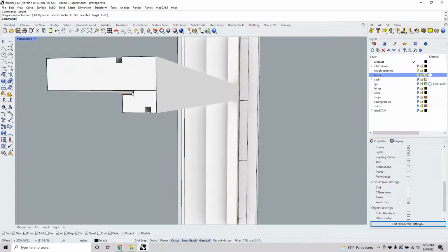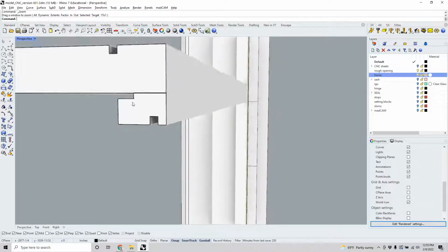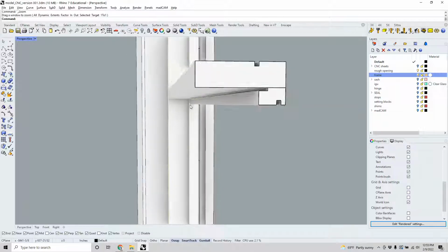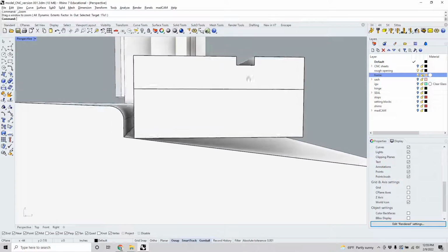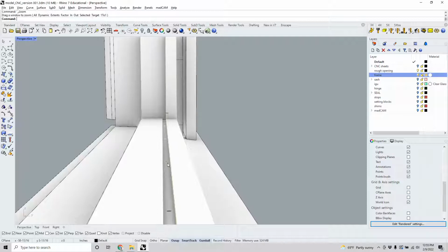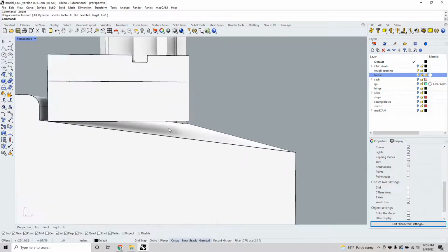And on the interior, what you see is this little pocket here. That curved pocket is to accept a weather gasket seal. Now that pocket runs all the way to the top and then down the sides. Now at the bottom, similarly again, I have a weep channel and these little holes that will allow any water that gets back there to drain out onto this sloped sill and exit the building.